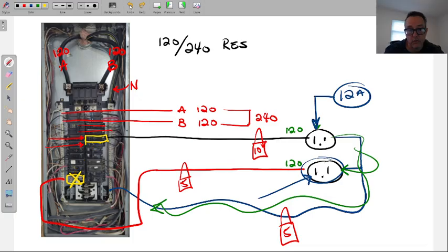So the thing you have to do, and people don't do it, they get lazy, is move this around. They would have to, for example, take this circuit here and move it to the bottom. Then you have space to put your other breaker next to that one. But people don't do that, and this is where we get hurt sometimes, because someone's sharing the neutral here. Is there any way to know that before you start putting your fingers in places?